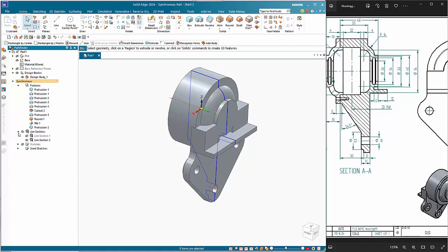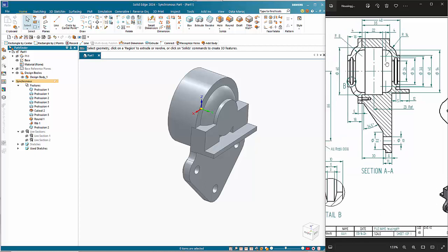So we've now got a couple, and one's in that direction, one's in that direction. And you can, as I said before, use that if you want to modify your geometry. Now to create the internal area, we've got a 26 by 60 bore, and then we can work off the center line of this portion here, and that's an 8mm radius.